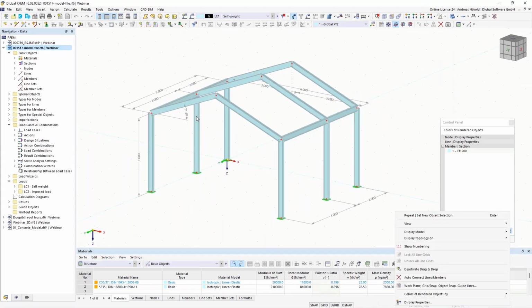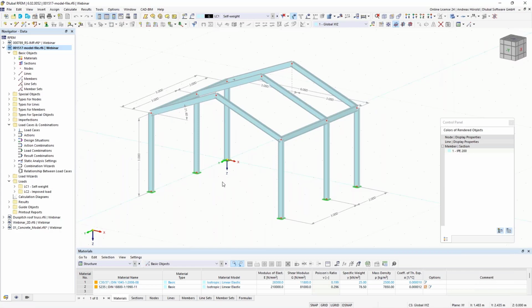Such a small steel hall, because the question is, where can I activate the lack of correlation in the load wizard of RSTAB 9 and RFEM 6? Now you can see this building with small height and so on. If the wind load for buildings or structures is to be determined by the simultaneous assumption of aerodynamic pressure and suction coefficients on the windward and leeward sides of the building, the correlation of the wind pressure on zones D and E of the wall surfaces may be taken into account.